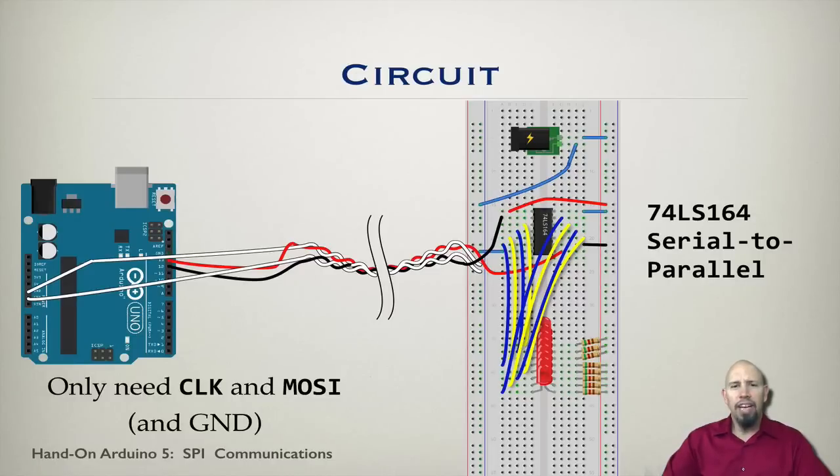You can also drive LEDs directly with the output, but it's a little more tricky, and in general you can get the light to be a little brighter if you do it this way, because generally the TTL chips cannot source that much current. They don't source much current, and so you don't get as bright a light as if they can sink more current. That is, they can take current to ground easier than they can source current. So we use that feature of the TTL chip in driving these LEDs. So this is the circuit that we're working with.